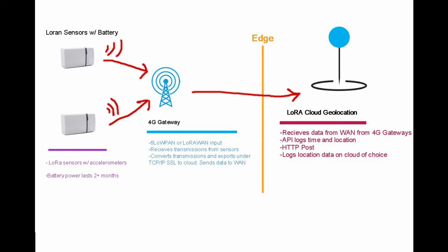These sensors detect if large changes in package velocity occur. We would have to also calibrate these sensors to minimize detection of the truck shifting during normal driving conditions. As the truck drives, the sensors will collect data periodically to reduce power consumption. At each red dot gateway, we utilize the nationwide 4G communication with LoRaWAN communication protocols. The sensors will dump all the data to these gateways.